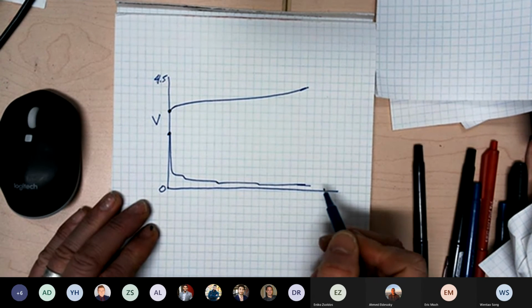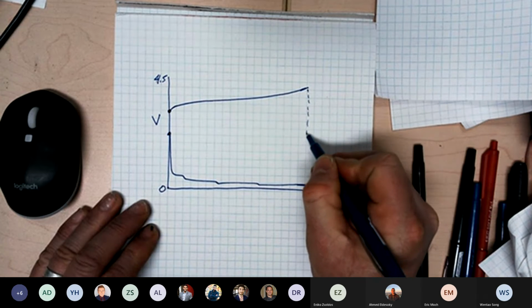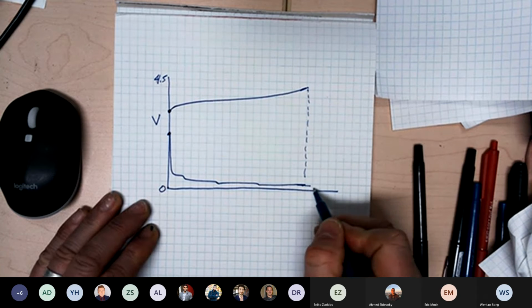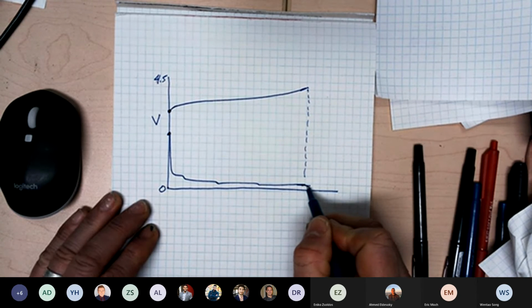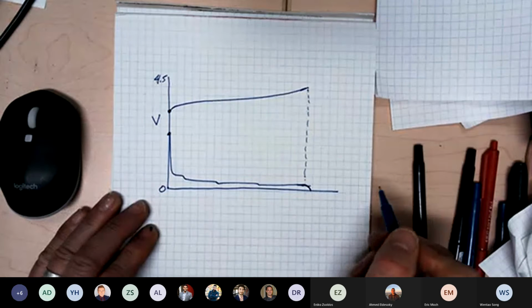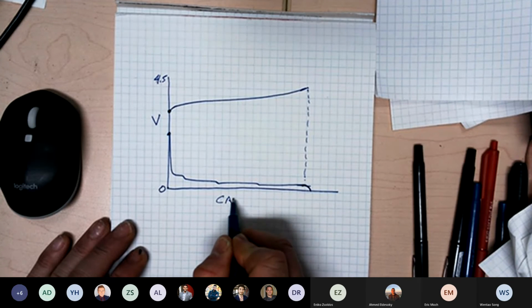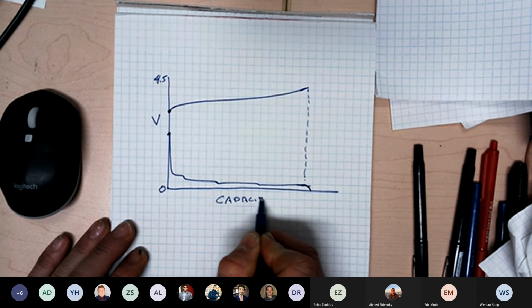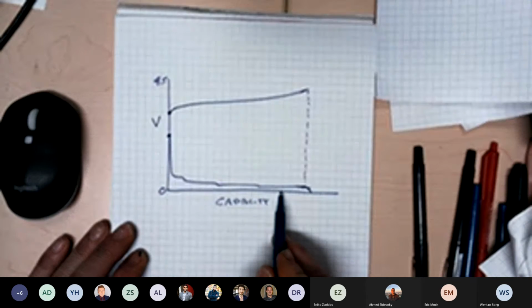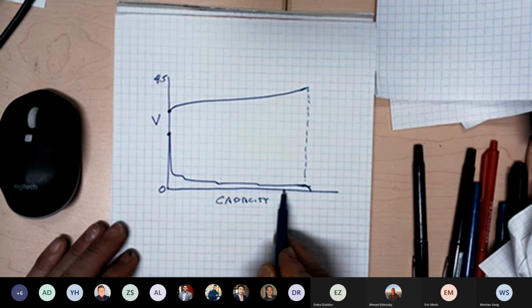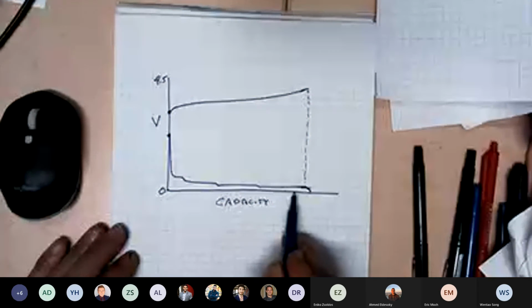and when the positive electrode reaches the top, as far as it goes, you want the graphite to be basically filled at that point. If the capacity of the graphite is smaller, for example, if the graphite terminated where my pen is at this exact second, and you continue to charge the cell, you would electroplate lithium on the surface of the graphite, which you don't want to do.